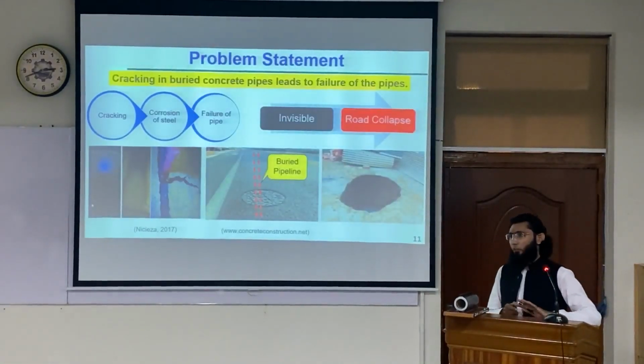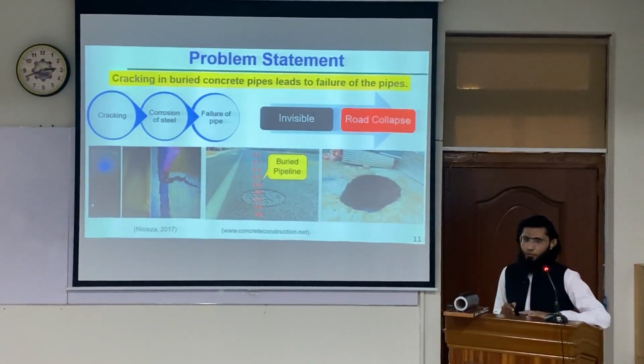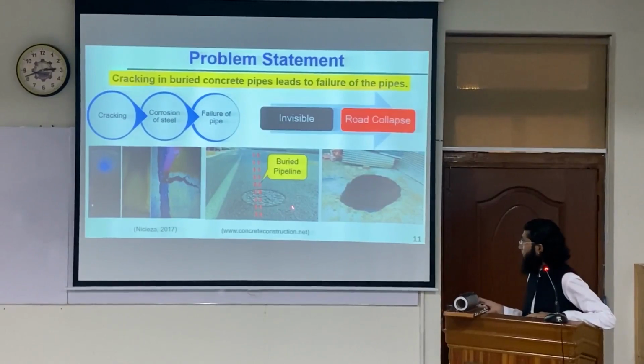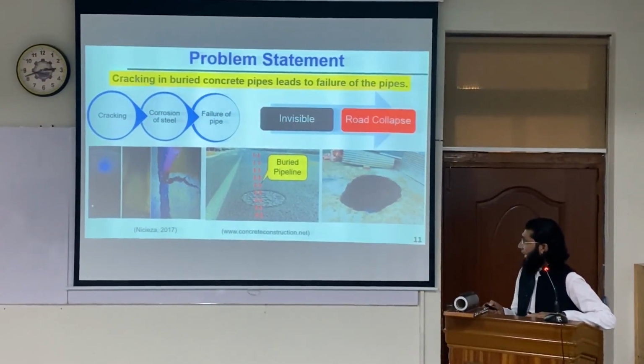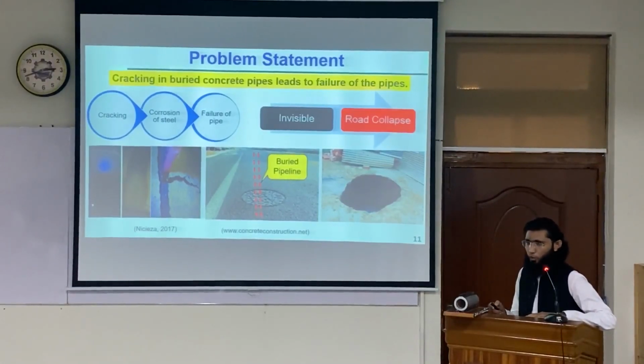Now, concrete pipes are always buried structures. This means when the cracks appear, they are not visible, which means the failure is apparent only when the road collapses or the settlement takes place due to leaking wastewater. Now, this means that the crack resistance has to be improved for the concrete pipes, because once they are put into place, the chances of remedial measures are limited.